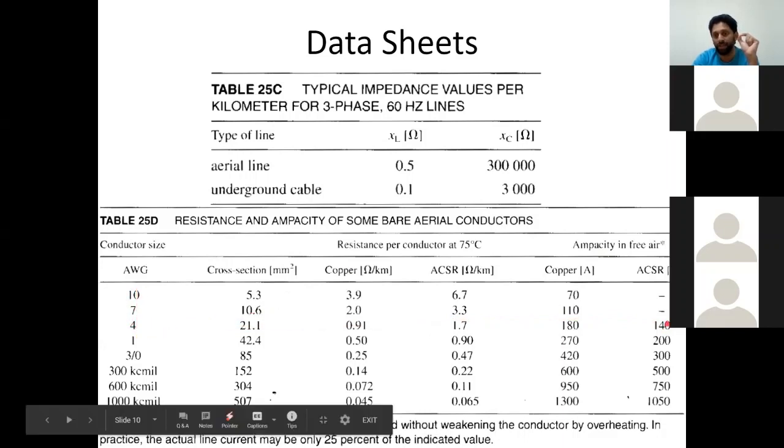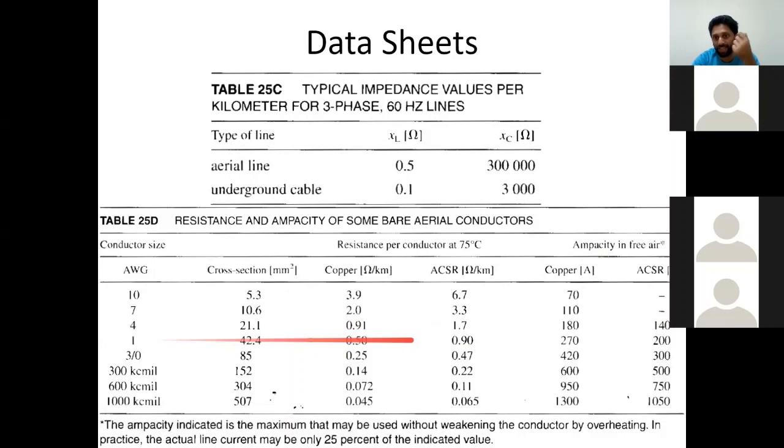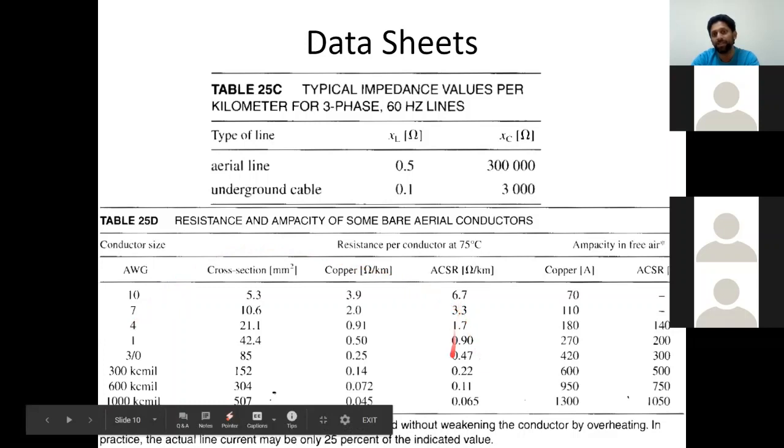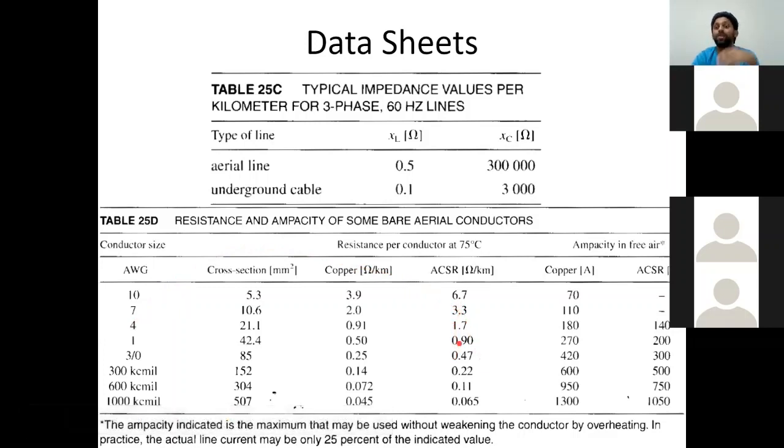If it is more than 140 and less than 200, you can use wire gauge 1. So based on the current, we will decide the wire gauge. Based on that wire gauge, you will calculate the resistance. These all are connected together, and to get current, you must know voltage. So first, the voltage table which we studied before is important. From that, we will get voltage.